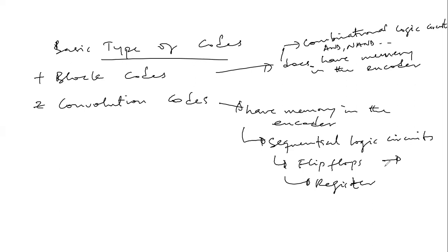So it means that for block codes, each encoding operation only depends on the current input message and is independent of previous encodings. Once we feed in our one, we know what we are going to get instantaneously. But for our convolutional codes, once we input our one, let's assume we have about 3 registers here.